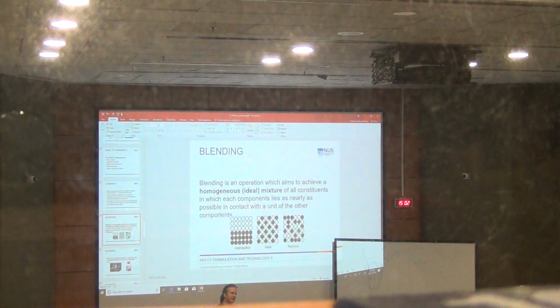Usually, the Brazil-nut effect always has the overweight in these two, except if you have the same particle sizes. Then, if you have different particle densities but the same particle size, you have sedimentation. If you have very huge particles, usually the Brazil-nut effect is the one in charge, which just has the higher impact on the powder mixture.